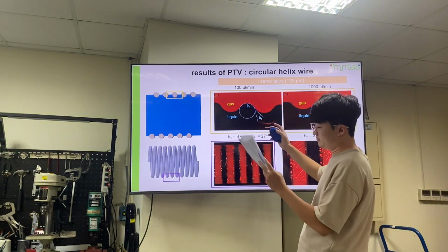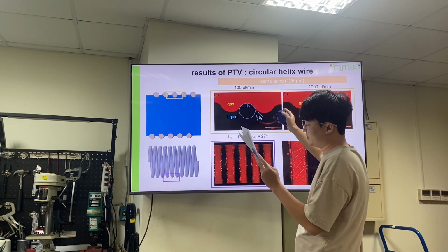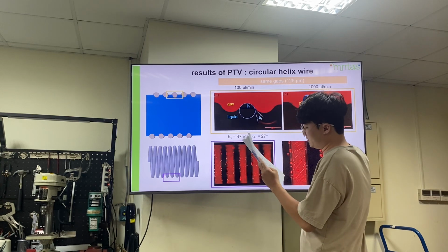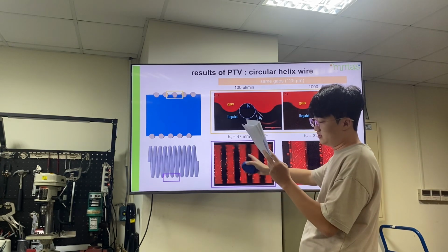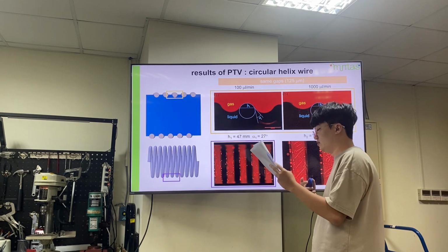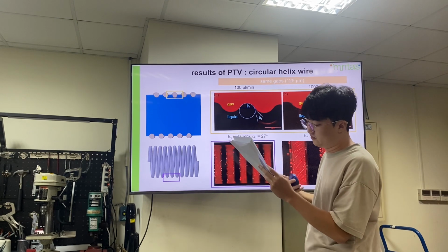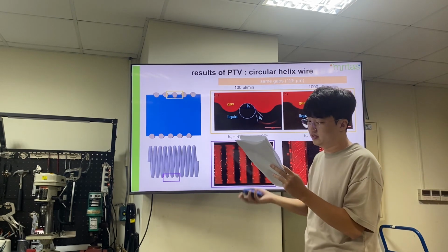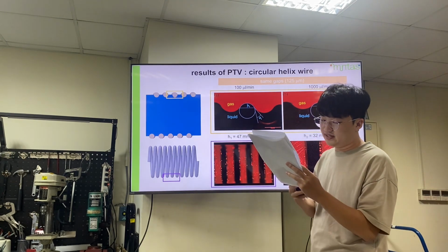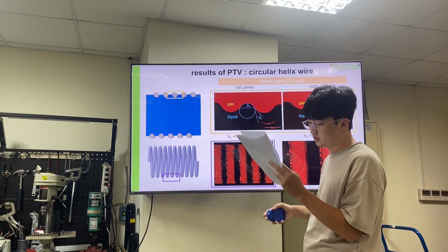Under the same gap width, observing the liquid air interface at a different flow rate yields variation. It is speculated that the change in internal fluid pressure in the helix caused by the flow rate alters the liquid-air interface, thereby preventing the conditions necessary for the vortex formation.